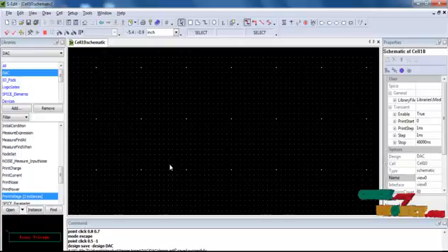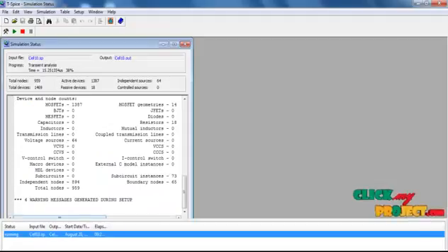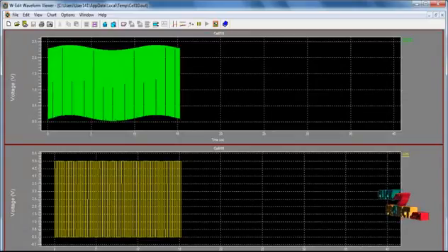First we have to design the test assistant block. Then, following this, we have to design the CMOS to CML conversion block. Then we have to design the D/A switches. Then finally the digital inputs will be converted into analog outputs. Then we have to see the simulation results. For that we have to run it. Then the simulation window will be opened. In this window, the digital inputs are given and the corresponding analog outputs are obtained.